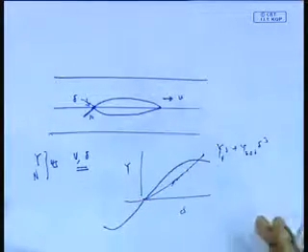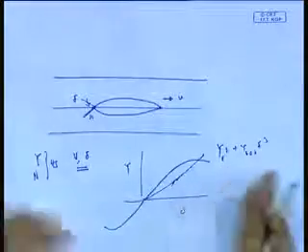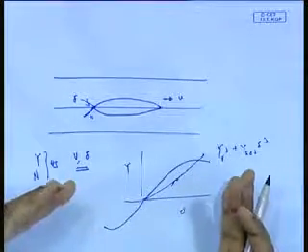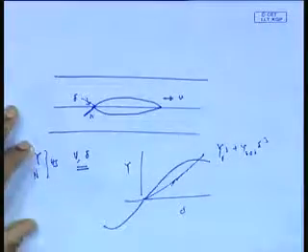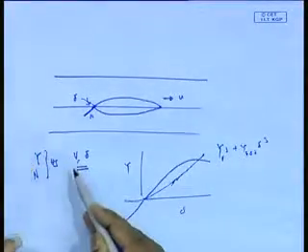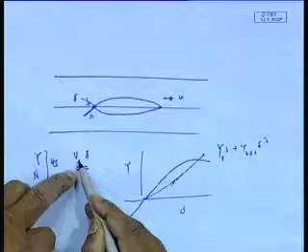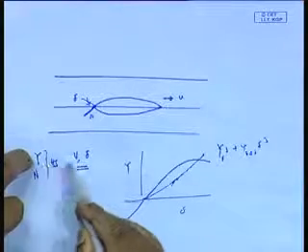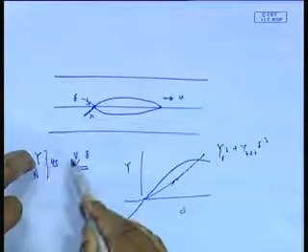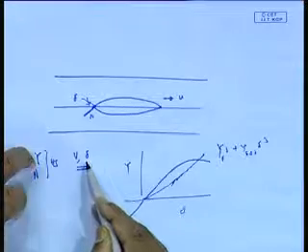These two can be varied, keeping the other constant. That means, among these, I can get linear sway derivatives, because Y versus V, V is sway motion, Yv, linear and non-linear.